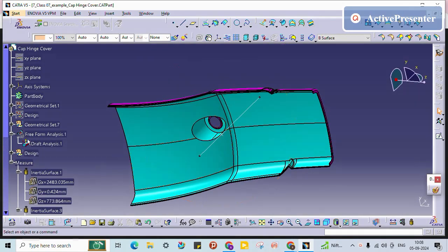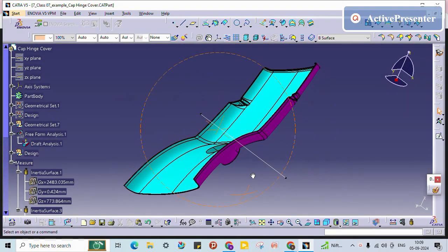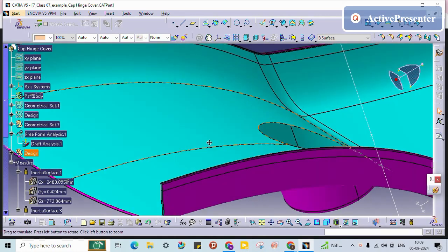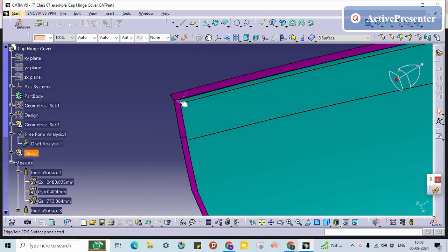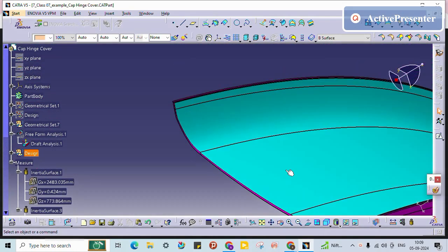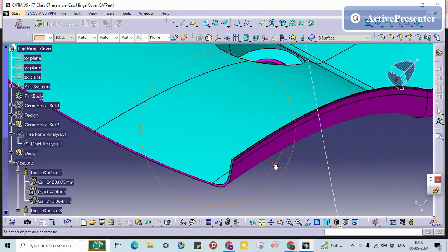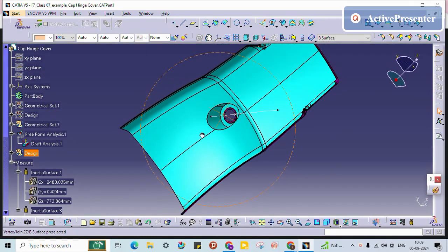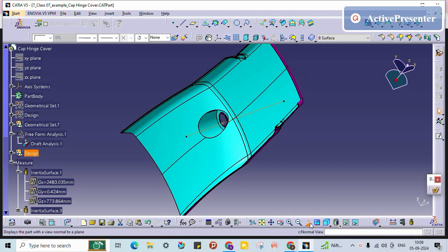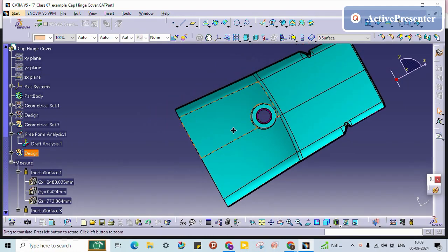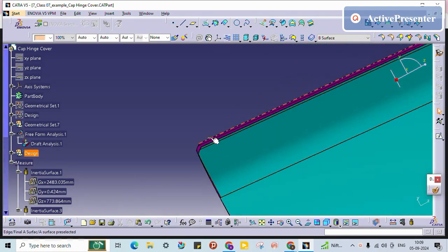Okay. So we will do this one later, like these issues. I will just tell you how to close the surface. See, in the tooling aspect, this area comes under your core side itself, so there is no need to maintain any draft here.